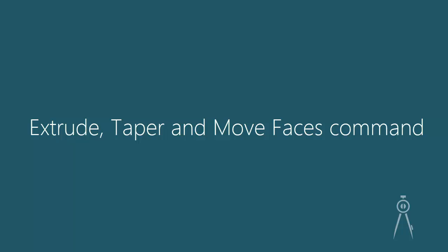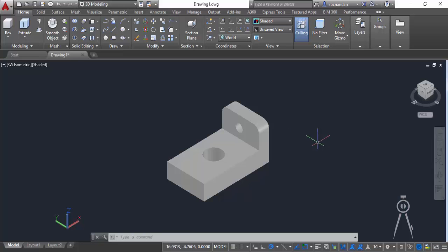In this lesson, I'll tell you about extrude, taper, and move faces command. So right now in this 3D geometry, we can selectively extrude some of the faces. For example, in this case, I'll extrude this face. For that, go to this flyout and select extrude faces.